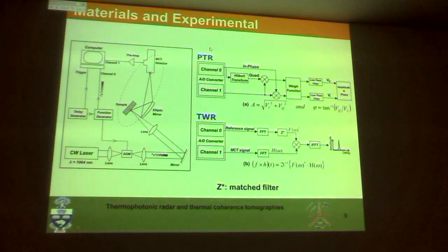And the detectivity usually is quite high if the spectral bandwidth is small. If you spread the spectral bandwidth of the infrared detector, the detectivity is low. So in many cases, you have to decide what spectral region in the infrared you want to monitor. Is this going to be a spectroscopic measurement? Is it going to be a measurement of a material that's opaque?